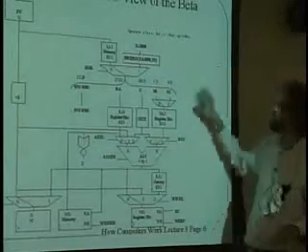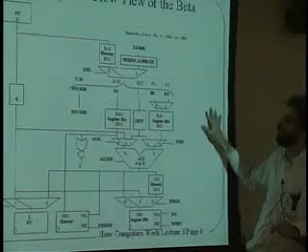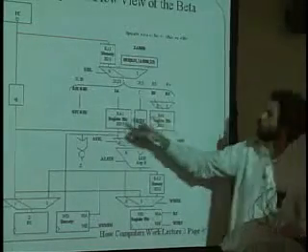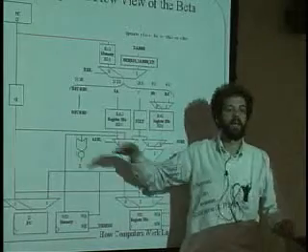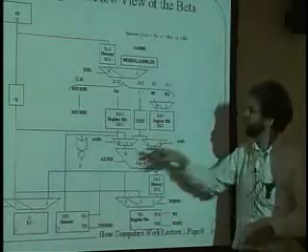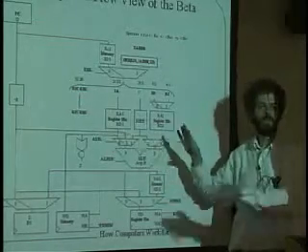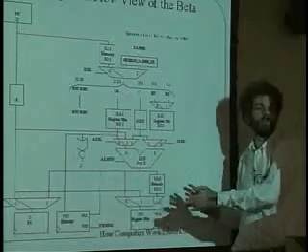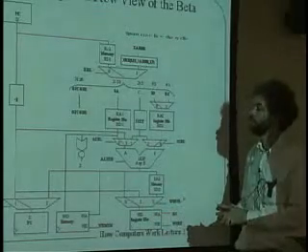And it turns out that there's going to be this whole cloud that we're going to talk about the next time, which is going to be the control logic, which will look at what the opcode is and have a table for every opcode. There will be a unique combination of ways to set each one of these selectors to sort of choose which way the data goes. Anyway, that's an excellent question.